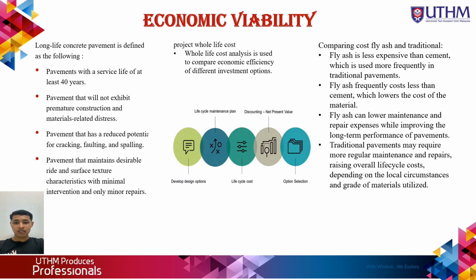Now I want to present about the economic viability. Long life concrete pavement is defined as follows. First, pavement with a service life of at least 40 years. Next, pavement that will not exhibit premature construction and materials related distress. Third, pavement that has a reduced potential for cracking, faulting and spalling. And fourth, pavement that maintains desirable ride and surface texture characteristics with minimal intervention and only minor repairs.